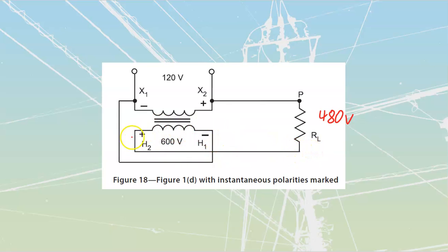The other thing that I need to analyze is, where does all my load current pass through? Well, I see it passes through this winding over here. And if this winding is only good for 25 amps, which it is because it's that 15 kVA winding, that would mean that I could only ever get 25 amps out to this load. If I take that volts and that amps and multiply them together, that would show me that the maximum kVA that I could possibly expect to get out of this transformer is limited to a value of 12 kVA. This is actually smaller than what the transformer's standalone rating was, right?